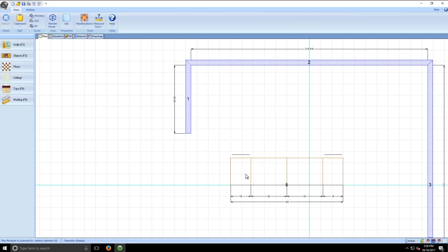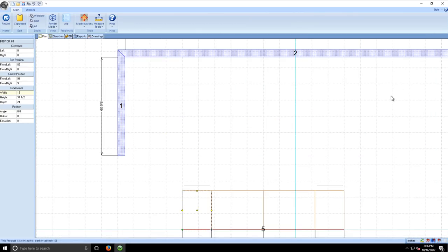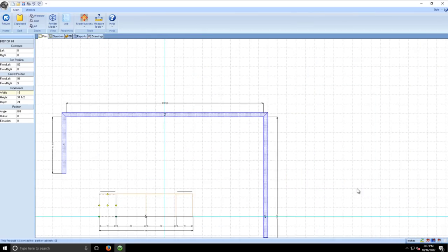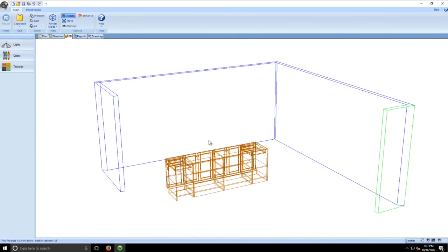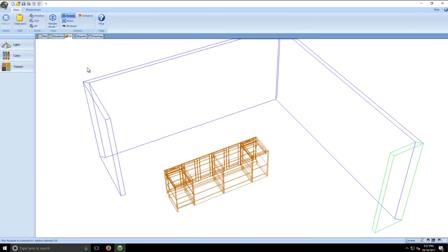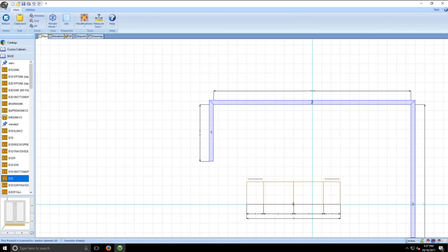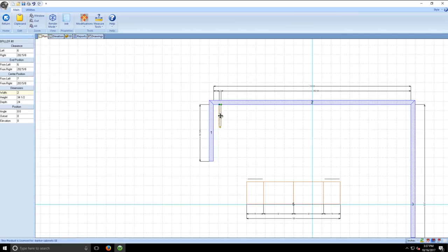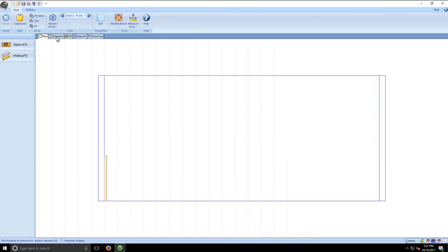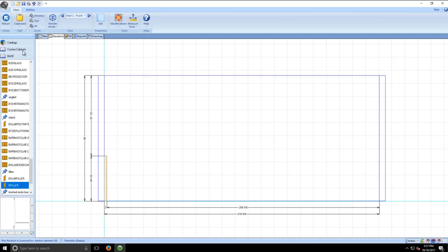Okay. So ultimately, let's go through and I'll just give you a quick layout here since we've already talked about the walls, how to move around the screen, how to go to our perspective view. We're going to move that thing. I'm holding the mouse button down. I'm pulling and moving it around. Okay. Let's go over here and let's just add a filler, usually down at the end. Base filler. All right, so I just added a filler right here. It's a 2-inch wide filler, real simple. That's what we recommend. Now let's go to elevation view, and then let's add in some cabinets.